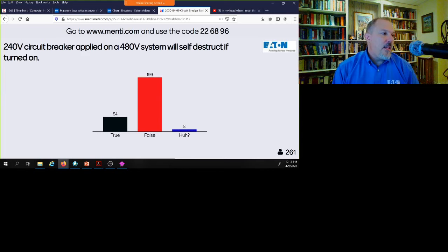Even if you exceed the interrupting rating, where you apply a circuit breaker or a fuse where the available fault current is greater than its interrupting rating, everything will work just fine until it's called to act. The moment that device has to do its job, that is when you could possibly have a problem, what we call, and Dan Neeser lovingly refers to it as, an unintended rapid disassembly in the field, right?